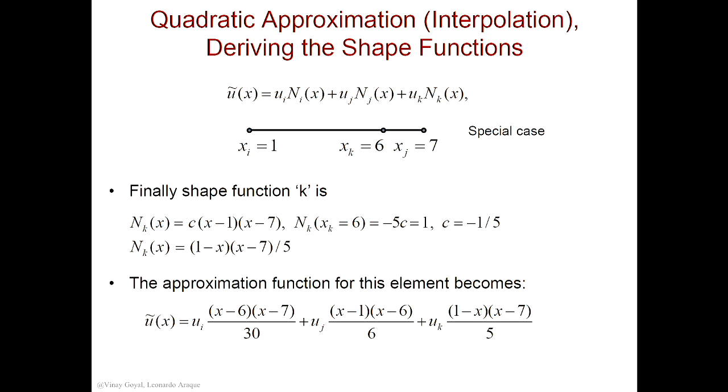So what the shape function is doing, first of all, is the basis function, which is very important because you're making the error, the residual function, orthogonal to the space of basis functions. The second thing the basis functions, which are the shape functions, are doing for you is allowing the unknown coefficients to be ones that have physical meaning. In addition, the basis functions actually have shapes, and they allow you to have two important properties, completeness and convergence, and we cover that.